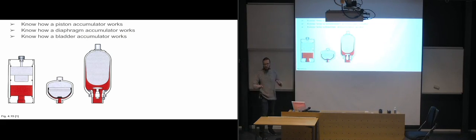So basically a battery of hydraulic energy where you can store pressure while your pump is working, and in case of, for an example, an electrical cutout, so you lose electric supply to your system, the pump stops working, you will still have some amounts of hydraulic energy left inside your accumulator, so that you could potentially perform a set of actions to sort of reset your system and get it to a point where it's not going to be dangerous to just leave it there. For an example, if you have a production line or something like that, you can have enough energy to sort of get all of the processes stopped before something bad happens.